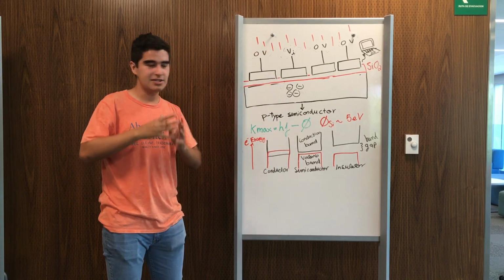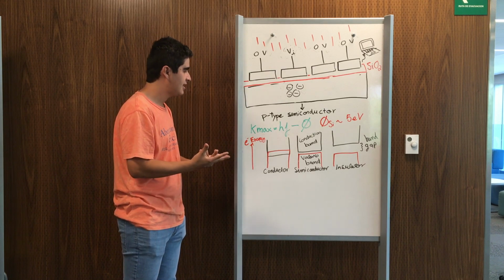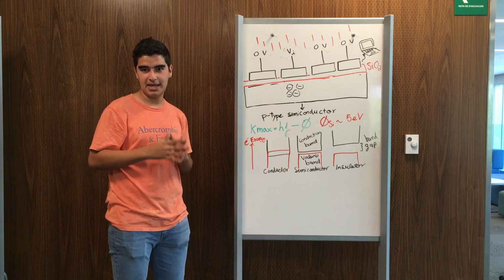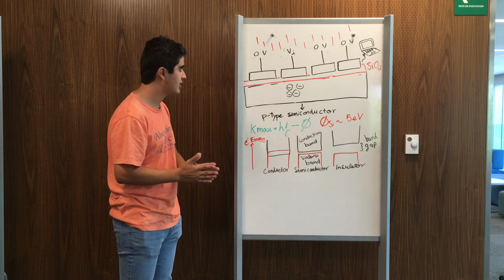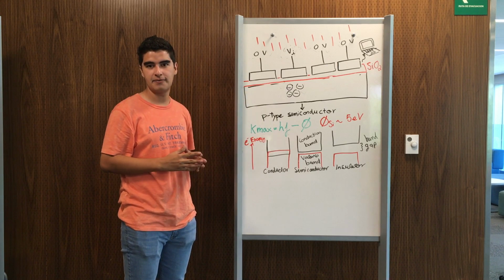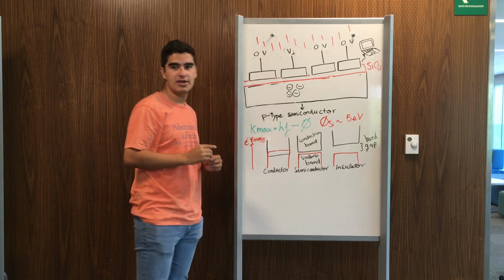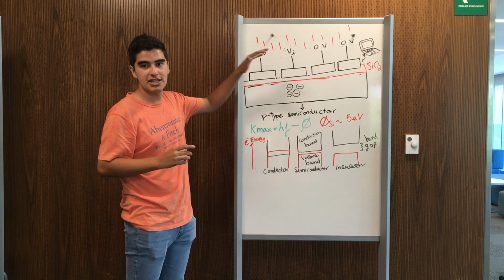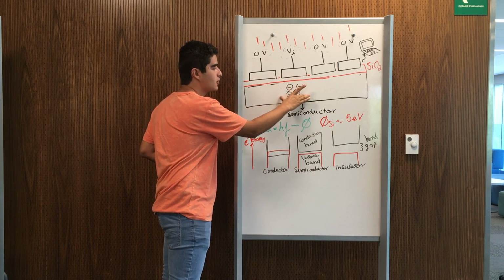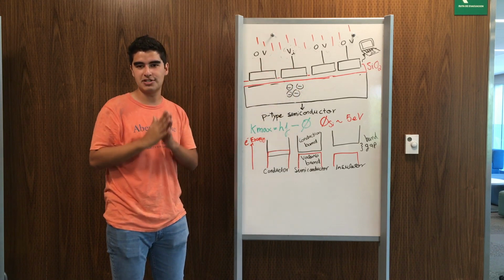When light is incident into the sensor, if this light has enough energy, then following the principle stated by Albert Einstein in the photoelectric effect, it will produce photoelectrons in the semiconductor layer. Because the electrodes have a potential difference in the first layer, charge will be stored below the electrode that has a positive potential.